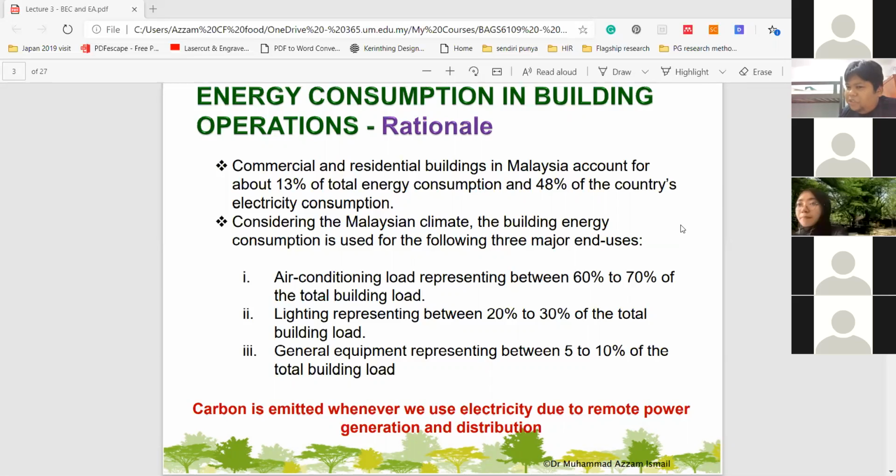And then if you can make some changes to your air conditioning, usually the aircon has got 2 units. One is the compressor outside, and you have the diffuser inside the building, right? So relocate the compressor, which is sitting outside, to a location which is shaded. Otherwise, if you can't, you just put a small awning over it, or put some shading over it, or perhaps plant a tree, or put a series of potted plants close to it, just to shade it. The idea is, once you provide shade, it's 2 or 3 degrees lower there, so the compressor does not have to work so hard in order to cool down the space.